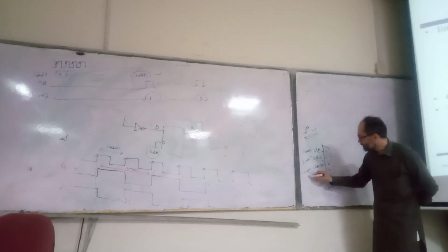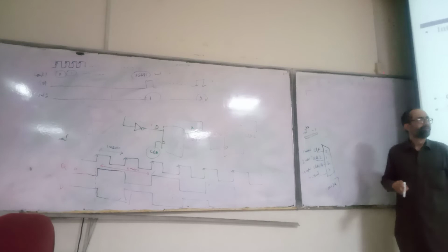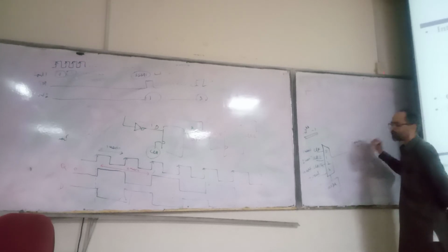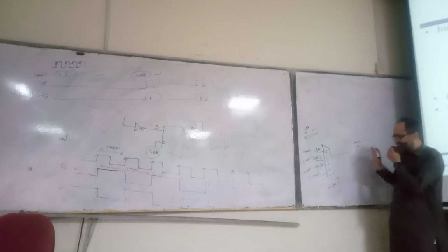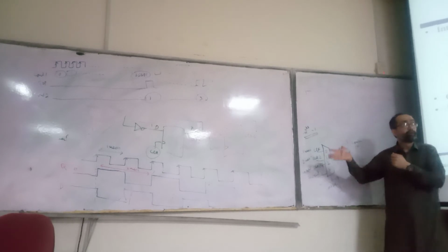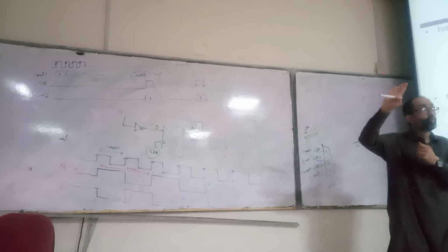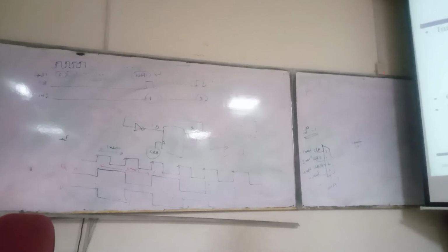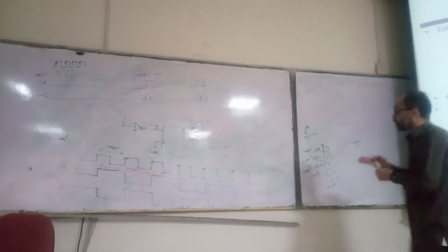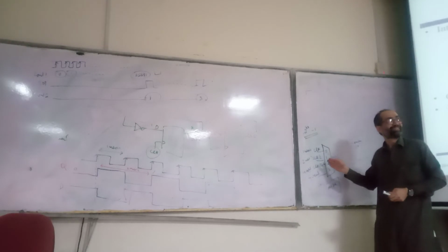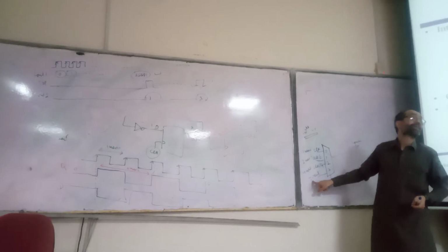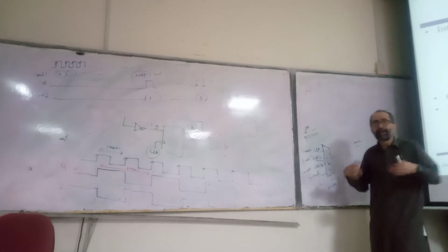And for the fourth, you can have a mode register and just generate an event. So now it's a counter, a 16-bit counter, or any counter you can use. Now if you look at this structure, it is supporting clocks with multiple frequencies, which is a trade-off between different resolutions and different ranges. And it's not only supporting clocks with different frequencies, but it's also supporting events. So it's a multi-purpose counter.